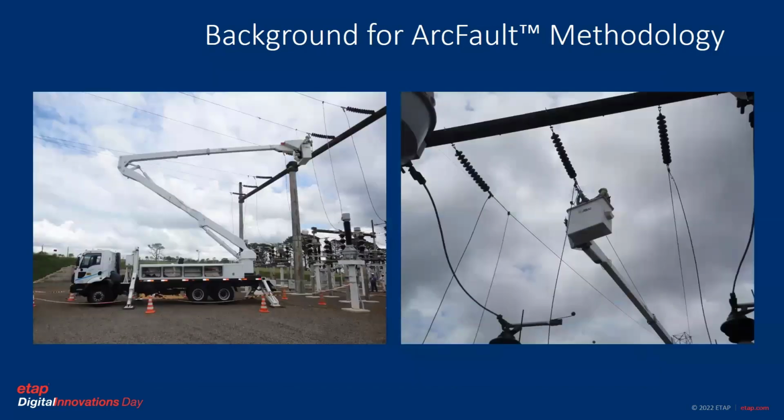The most likely type of arc in overhead conductor systems is the line to ground arc fault. This is why NESC and OSHA have given emphasis to this type of fault and provided some basic guidance, such as is provided in the National Electrical Safety Code in table form to estimate the incident energy for this type of systems.